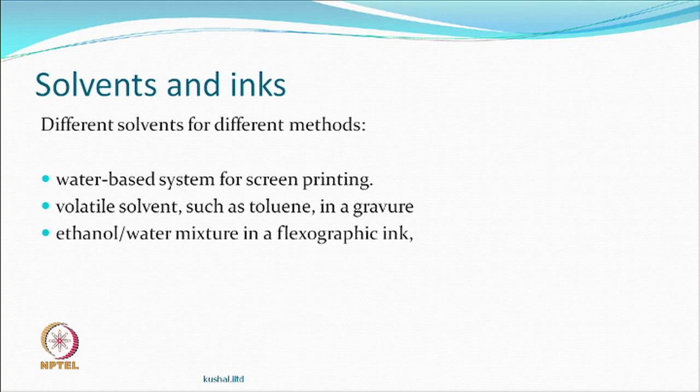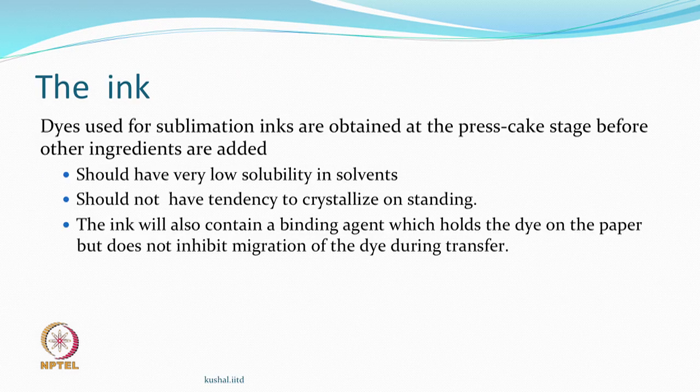For flexo, people use ethanol water combinations, medium, and for litho, people may use drying oil which can dry easily, but it's all oil, as you know. You are dealing with hydrophilic, hydrophobic principles in this type of printing methodology, and therefore, you would like to use an oil which dries, and obviously, it is only oil because it does not like water. That is the principle of the technology.